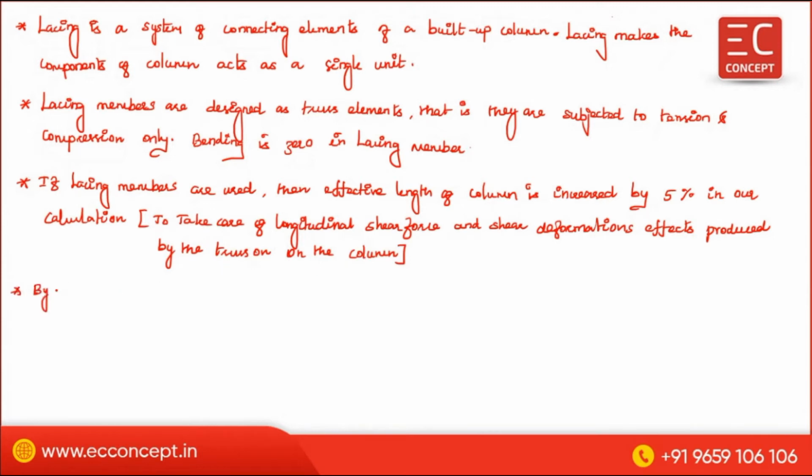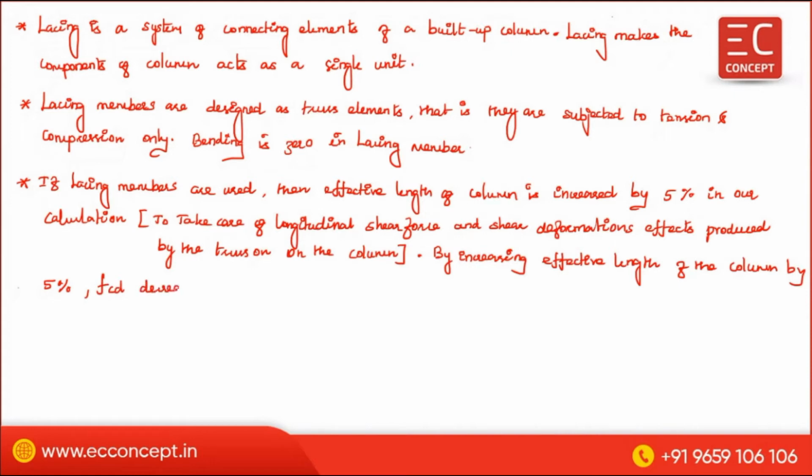Now, a continuation of this point: by increasing the effective length of the column by 5%, the design compressive stress FCD decreases. So the AG provided will be more.